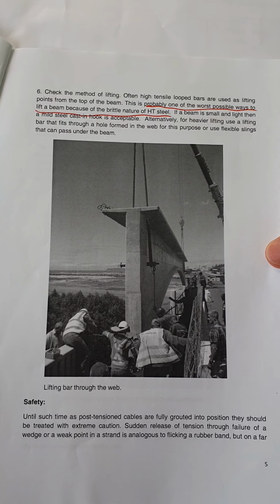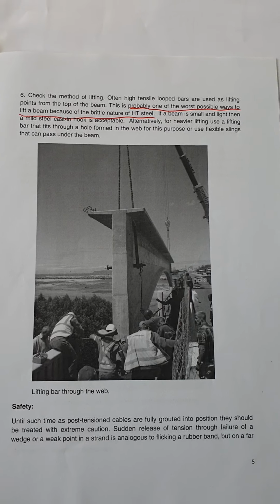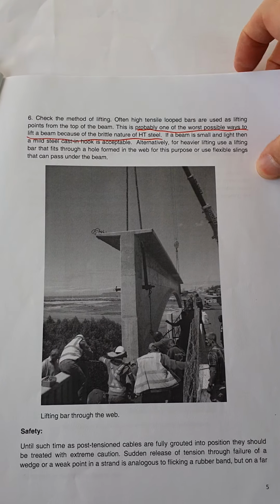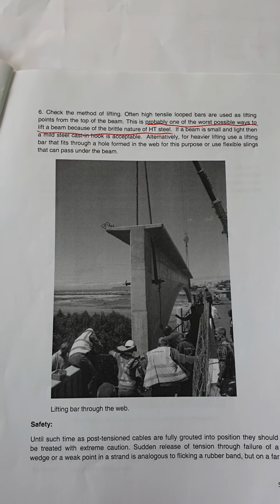Often tensile loop bars are used as lifting points from the top of the beam, and this is probably, in my opinion, one of the worst possible ways to lift a beam because of the brittle nature of a high tensile steel bar.